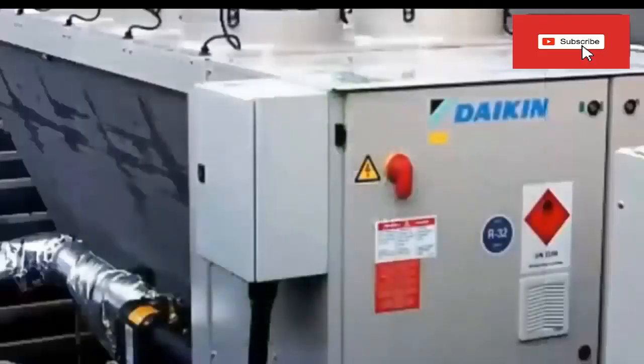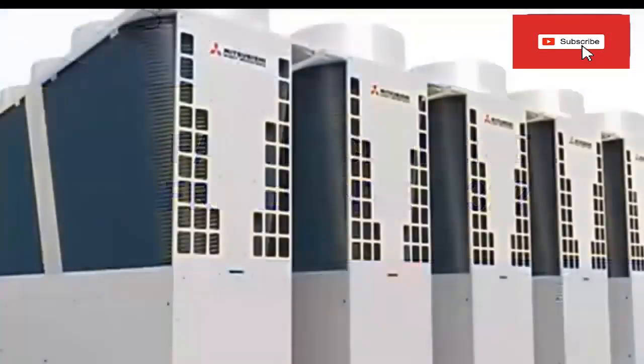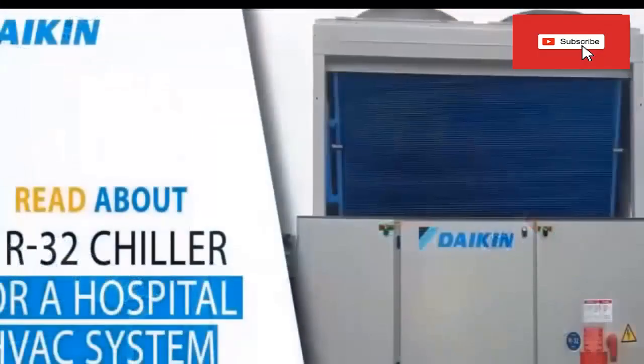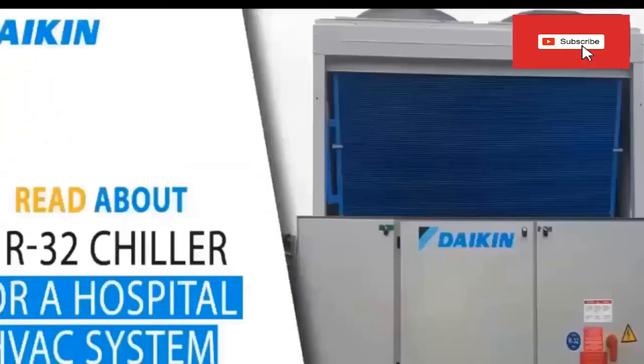Before we finish, we must answer two typical questions. Question 1. Is R32 refrigerant easy to ignite? R32 refrigerant is actually difficult to ignite, and requires certain conditions to be met. A. There would have to be a significant refrigerant leak. B. The leakage should be sufficient to reach a lower flammable limit concentration. C. There would have to be an open flame or high-energy ignition source, where the concentration is sufficient to ignite the R32.